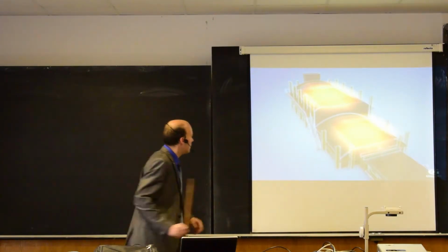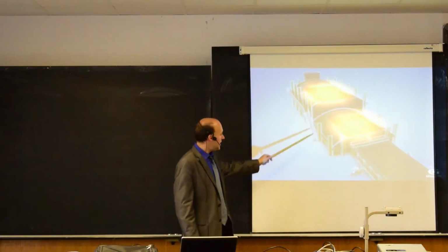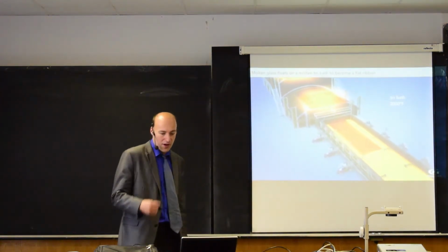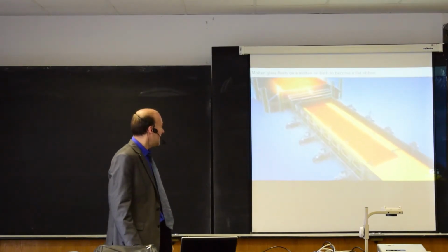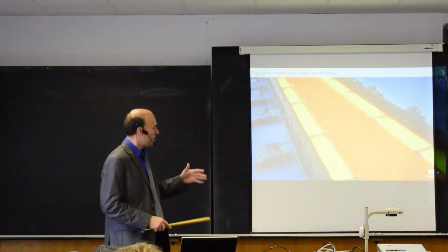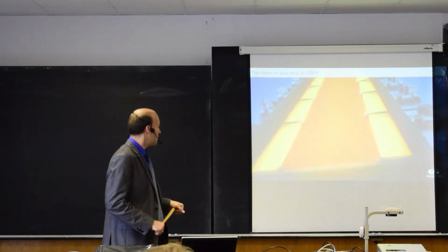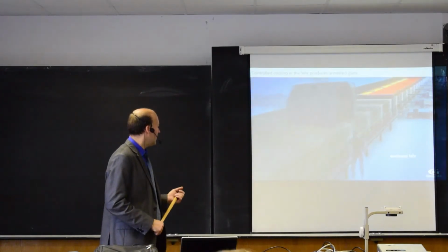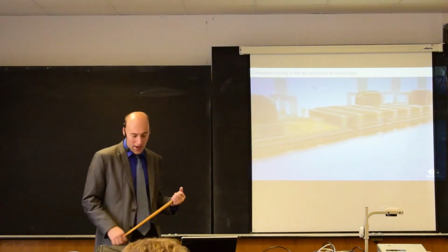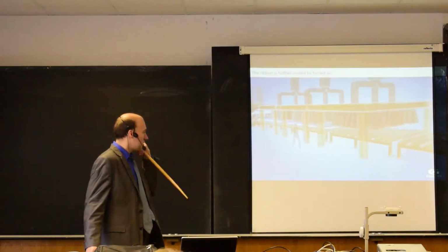So it's the furnace where we measure the temperature and gradually it cools down, and now it's being pulled out over a thin bed, and that's the reason why it's so flat, and we need to monitor temperature continuously during this process. That's an example where you can find non-contact thermometers, because there's really no other way to measure the temperature in this kind of application. So you see now it gradually cools down, and at the end it's cut into sheets of glass.